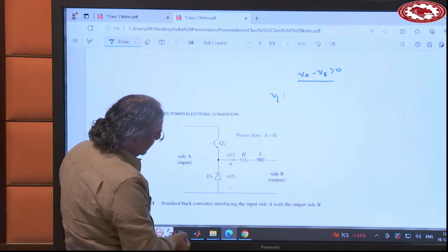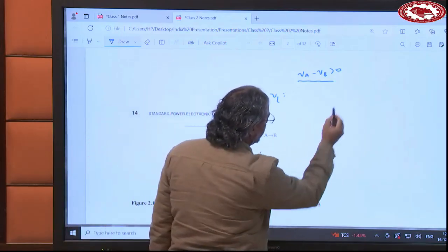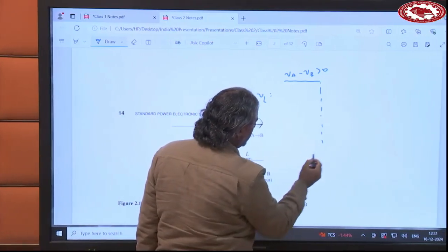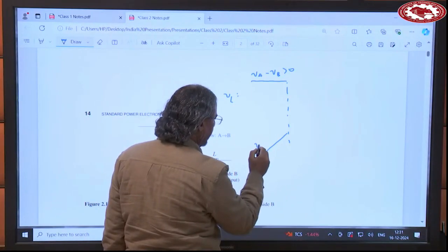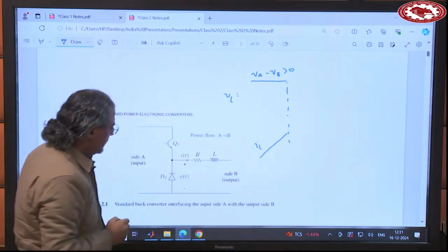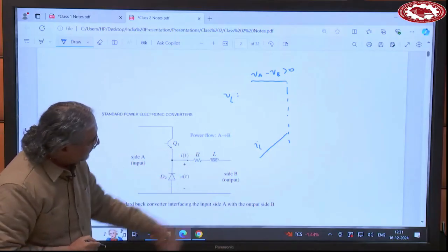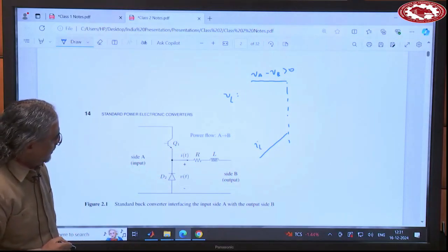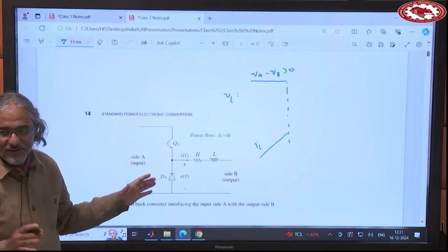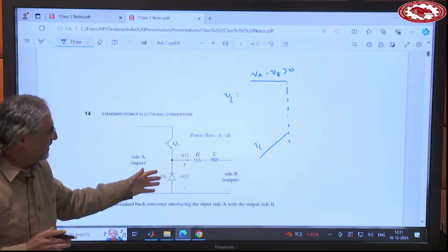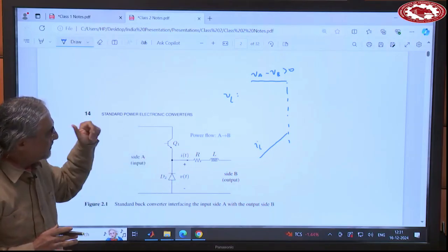When it's positive, the current will start going up. So this current, IL, or I, basically, will start rising. If you just keep it like that, this current keeps increasing and will damage the inductor, right? But at some point, you turn off the switch.